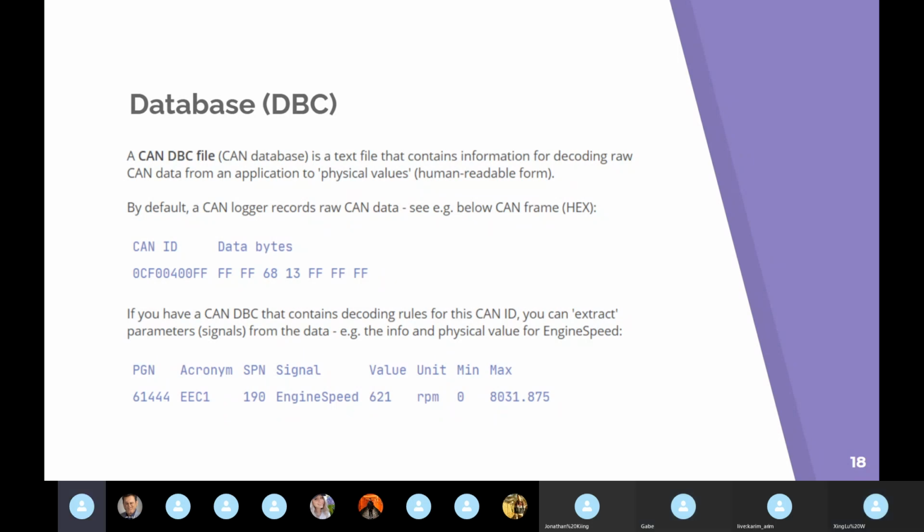And just to add on for the dashboard side, I think there's a really nice Python package called CAN-Tools, which parses DBC files and can encode and decode a CAN message. I haven't used it, but it looks promising. That's good. I'm glad we're using Raspberry Pi and Python because they did a lot of the work for us, and that's going to be higher levels of code. For TMS 570, I have to tell every part of CAN that it exists and what to do with anything that happens. So that's lower level. Yeah, no, that makes sense. It's very low level.